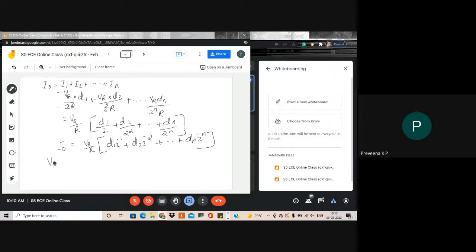How is the analog voltage obtained? What will be the value of this analog voltage? That is what we want in this case. So Vout will be equal to I0 into RF. From the circuit diagram you can clearly see the output voltage is equal to current into resistance. Which portion is connecting to this output voltage? The reference feedback resistor RF is connecting to this point, and the current through it is I0.